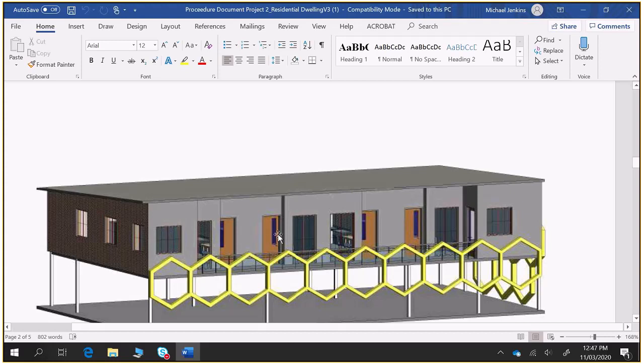You're also going to have to work out how you can provide disabled access to the apartment. Now, you've got 4 apartments here, but then you're going to knock a wall down in one of them to create a larger apartment for that disabled access. You have to ensure that your door widths are adequate, that your travel distances to required exits are adequate, and that there's adequate access for disabled people, and we'll be going through that more and more as we work through.